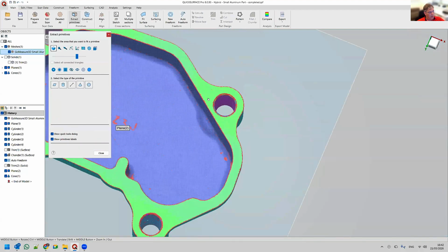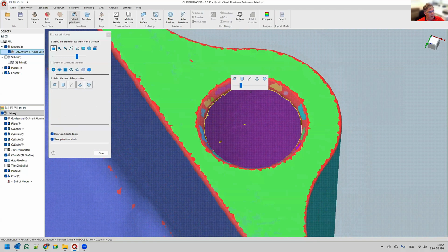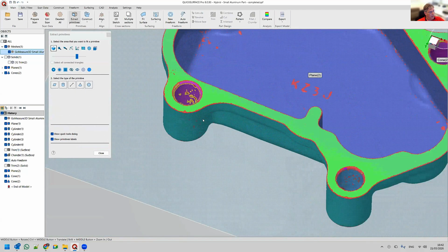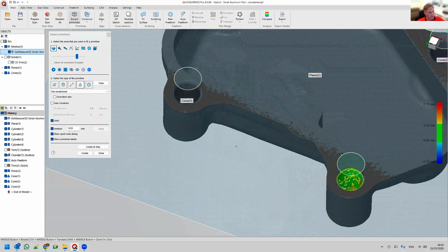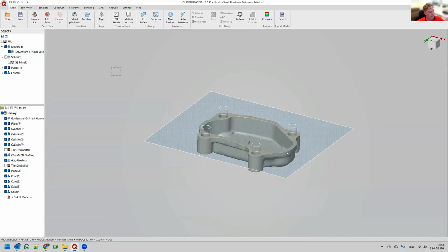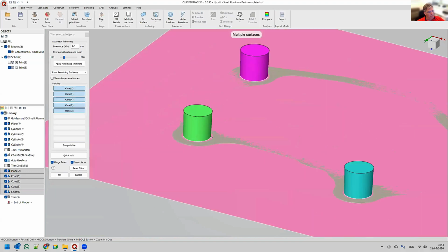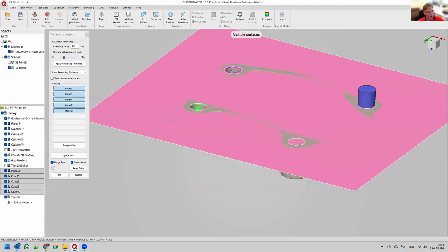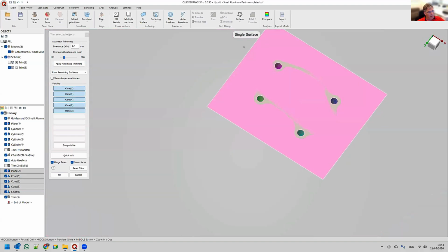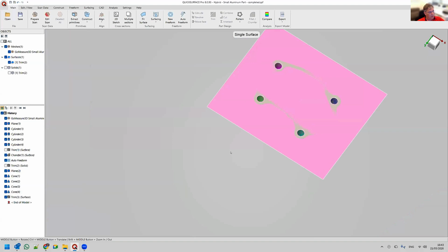I can just create this. And in this case, I will create these four cones here that I needed. We'll create and keep them. So I have these four geometries. What I can do is select everything and say I want to trim. How do we trim? It's very simple. You just pick and remove what is not needed. You remove the excess surfaces, and you can see it tells me it's a single surface, and I can press OK.